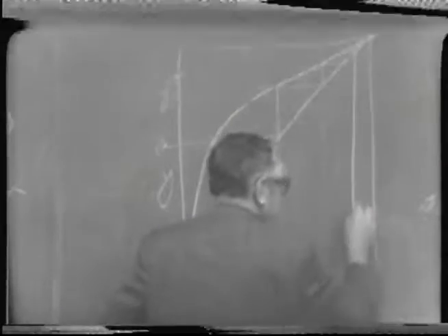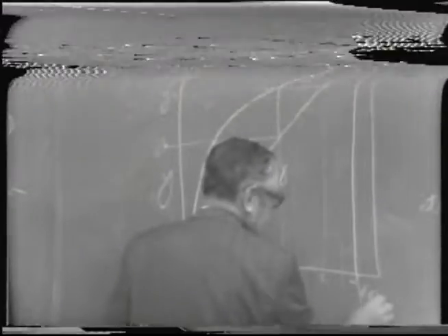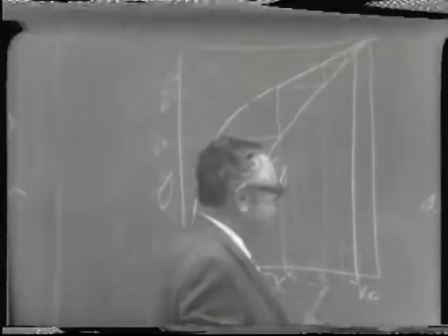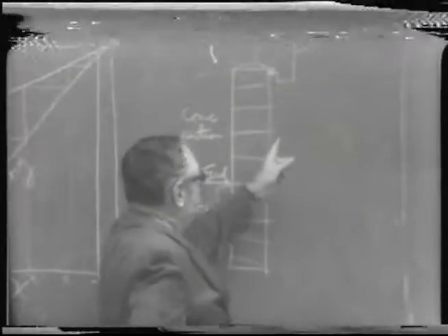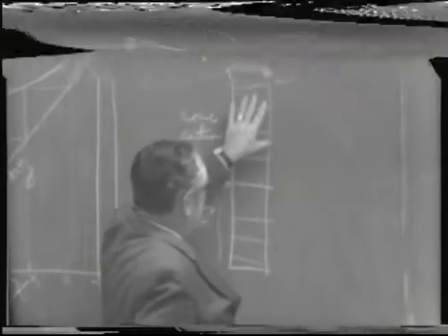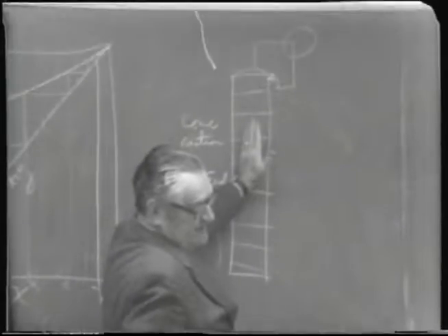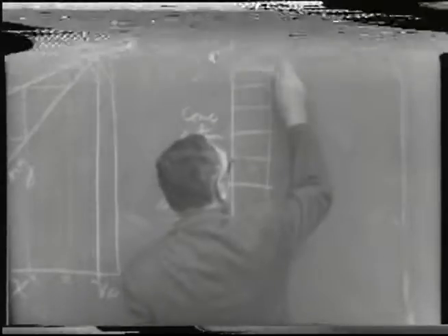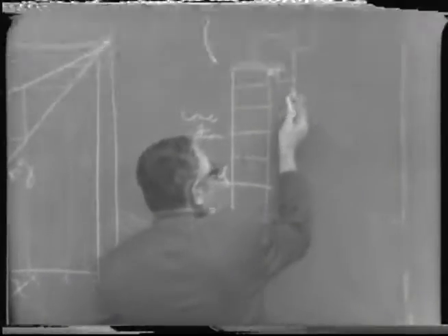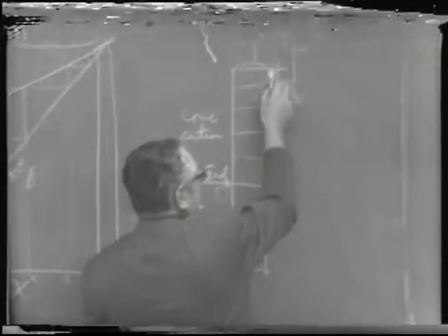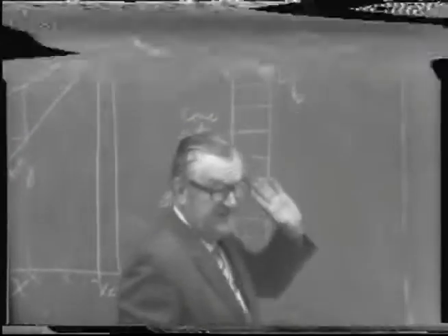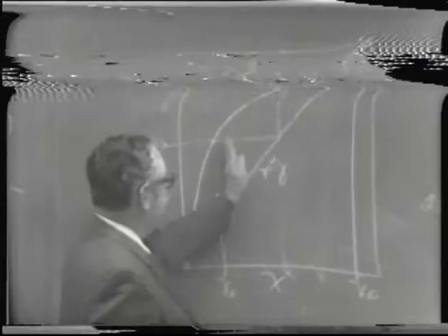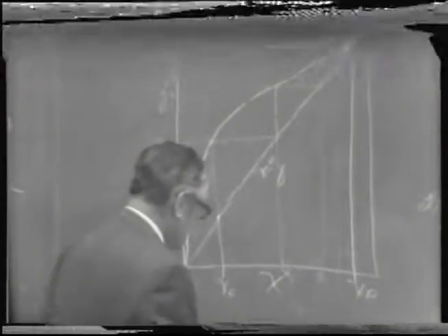If we desire that this be the product, X sub P, we have to have some finite reflux ratio. In other words, over here we had an infinite reflux ratio. If we're talking about the ratio of the amount of liquid run back to the amount of product taken out, and we have no product taken out, well, we'd have L over 0, which would be an infinite reflux ratio. And that's the only special situation where this first chart I've shown would apply.